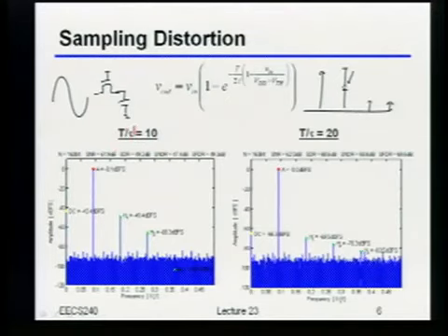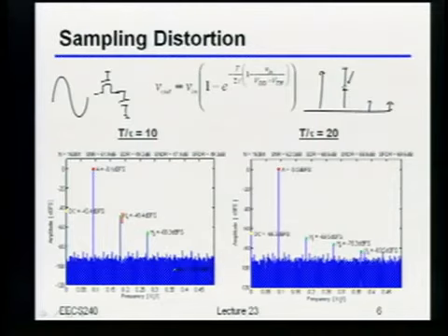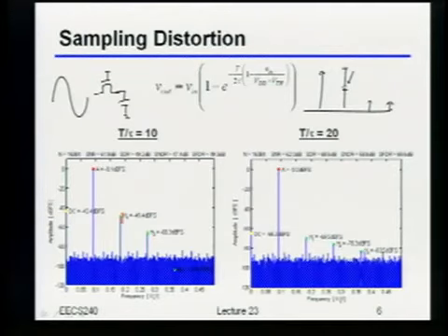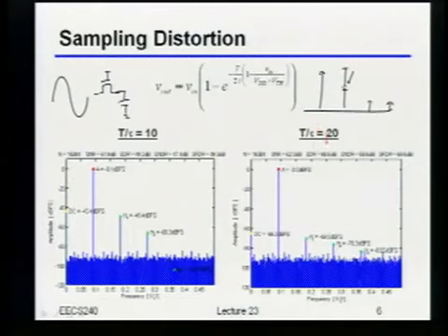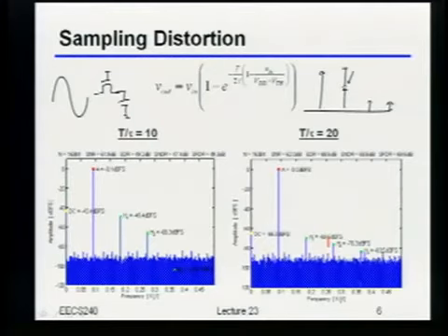Because notice there isn't a whole lot I can really change here, right? I have a certain switch that I've sized to meet, let's say, a certain bandwidth. And if I'm trying to run at this particular speed, sorry, that's the distortion that you get. In fact, from a design standpoint, the only thing you can do to improve this is over-design the switch. As an example, if I made the switch twice as fast nominally, now you can see the distortion is down at something like minus 70 dB. So I gained myself an extra 3 or so bits, right?